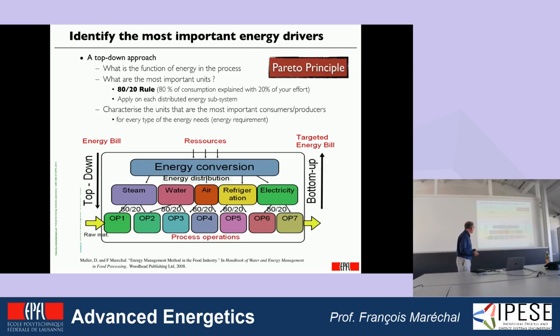And what we will do there is that we will identify in those process units who is mainly consuming steam, for example. And as soon as I'm identifying that this unit is consuming steam, I'm going to calculate how much cooling water is consumed by the same unit and how much electricity is consumed. Okay? And I will do the same until I have explained 80% of the steam consumption for the different pressure levels. I will do the same for the water.